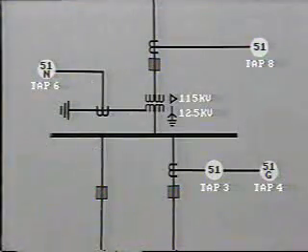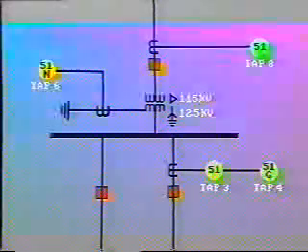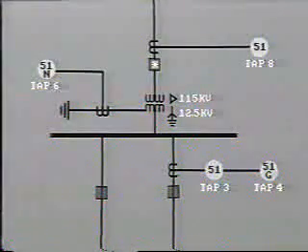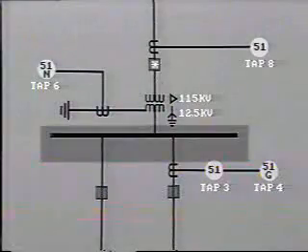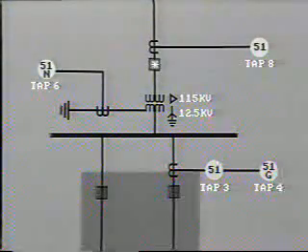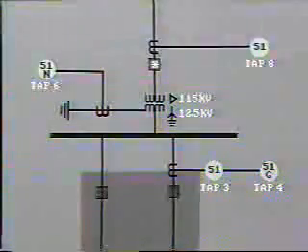Another arrangement here shows a circuit breaker on the primary with the secondary connected directly to a bus. Each feeder has its own circuit breaker and individual protection. The primary circuit breaker will trip for a fault in the transformer zone, or a fault on the bus, or a fault on any feeder, which fails to be cleared by its own primary protection.